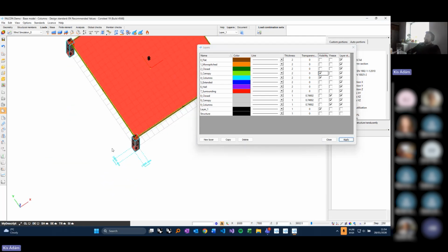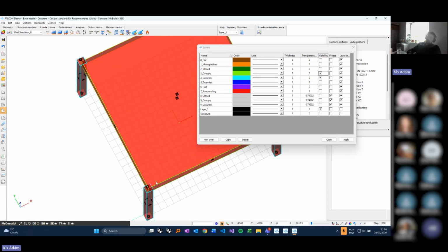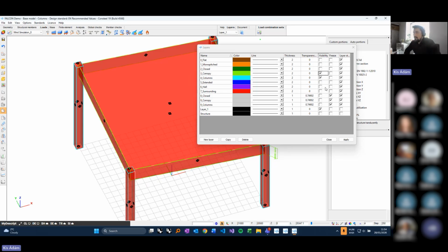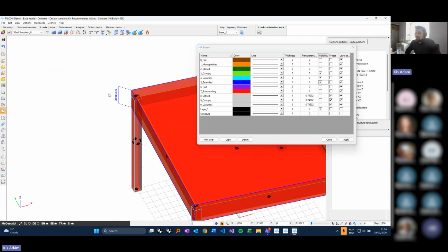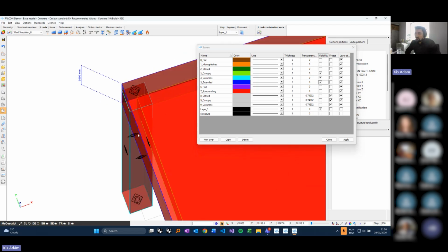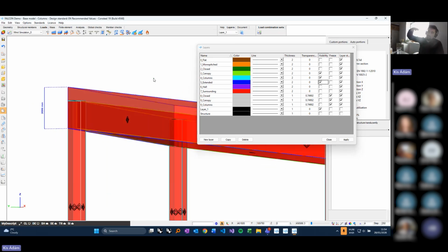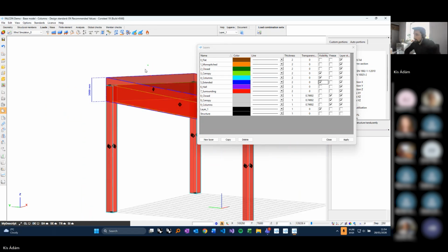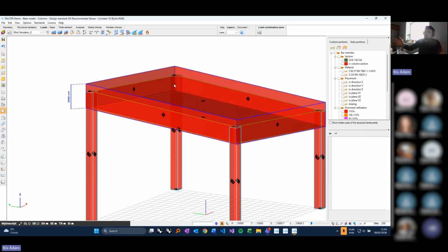In this case, you can see that I use the actual geometry of the columns, and because we are creating our wireframe models, these are not reflecting the reality, because our canopy has a certain extended geometry, because obviously our surface maybe ends at the edges of the columns, and maybe we actually have a higher building because we have a certain envelope, maybe a purlin system, a trapezoidal sheeting, anything else, and so we have a higher canopy, or a bigger extended version of our surfaces, which would raise questions.